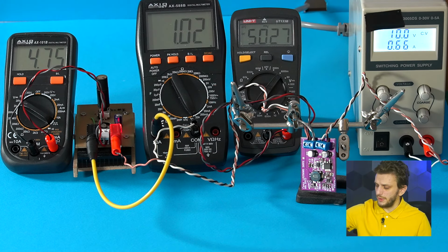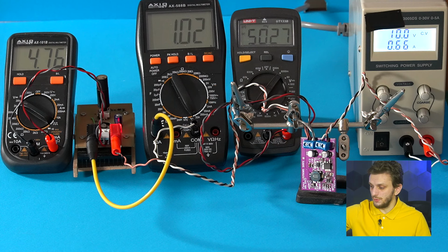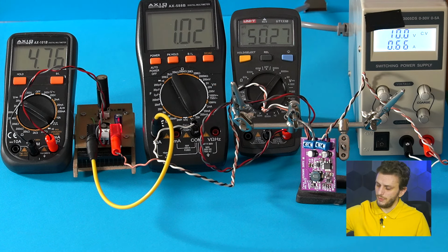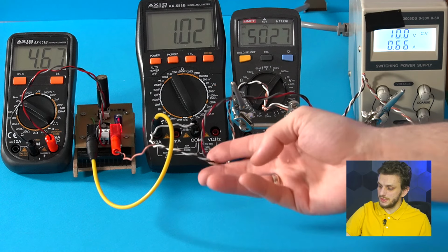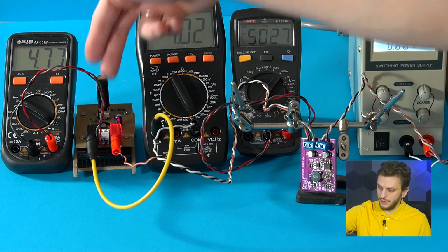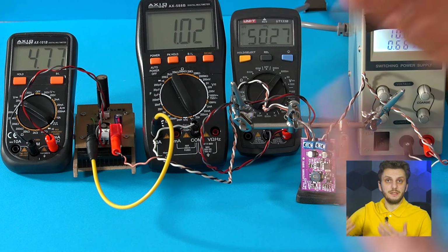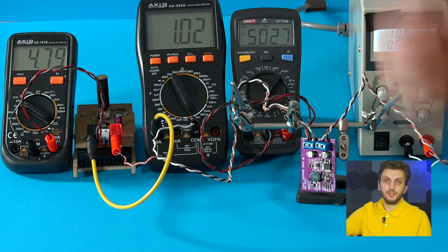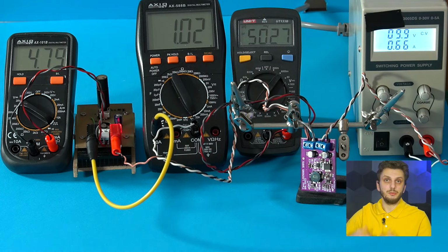so we go up to 1 ampere, we can see a very clear difference between what is at the power supply output and what reaches the load. So there's about 270 millivolts of voltage difference. Now this difference is proportional to the current that's being pulled by the load and the equivalent resistance of the wires, so the connectors between the power supply output and the load, both positive and negative lines together. So if we know this resistance and we know the current draw, then we can work out what the voltage drop will end up being.